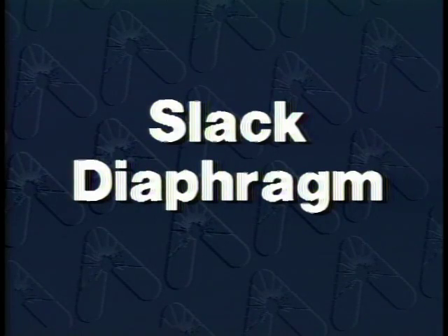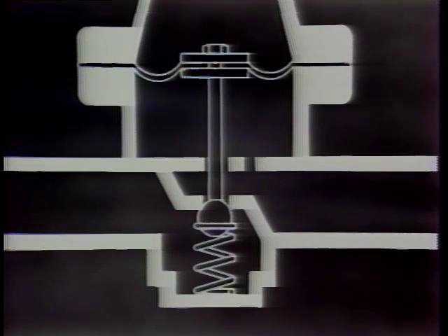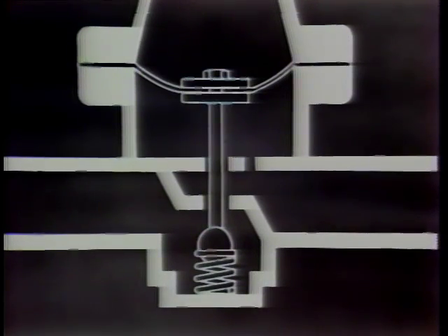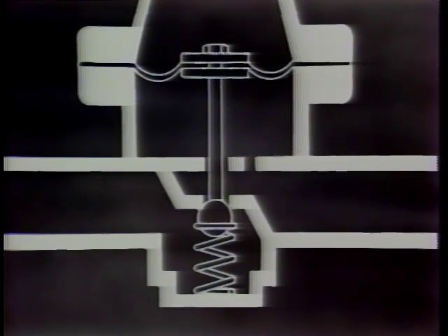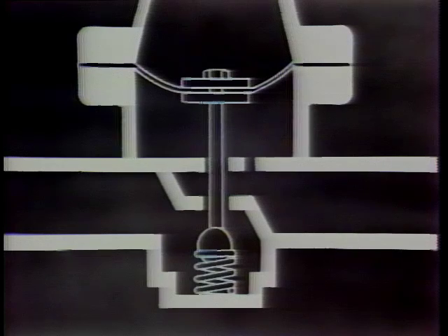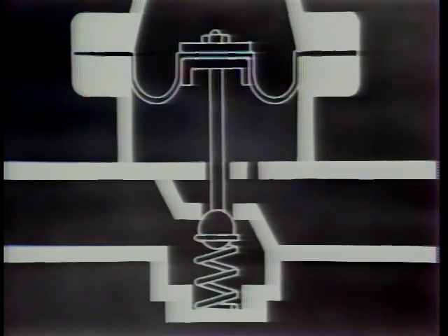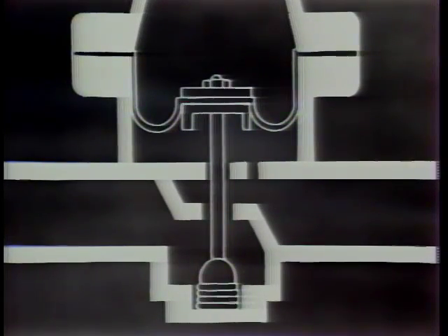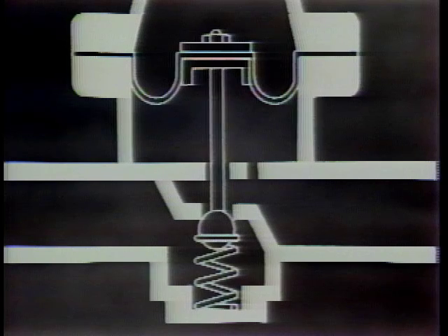The slack or grooved diaphragm has a groove molded into the outer circumference between the diaphragm plate and the valve body. This slack area allows medium-length valve travel with increased flexibility, resulting in higher flows, sensitivity, stability, and accuracy than a flat diaphragm. A further adaptation is the cupped diaphragm, or Bellophragm. In this case, the diaphragm fits quite loosely over a cup, allowing a long valve movement and an increase in stability. All diaphragms, however, are made from relatively thin stock, which severely limits pressure.